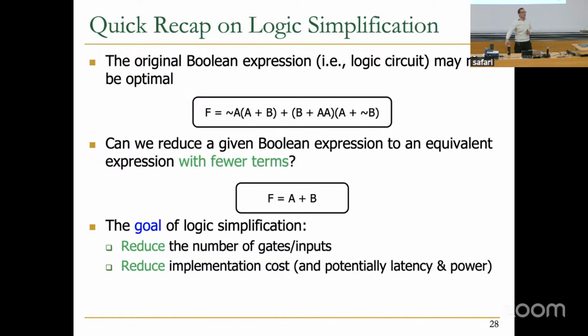So for example, 3 nanometer CMOS technology developed by TSMC, in a particular library that's optimized for low power, a 2-input AND gate has a latency characteristic, a power characteristic, and an area characteristic. So for every single gate, you may have these characteristics.